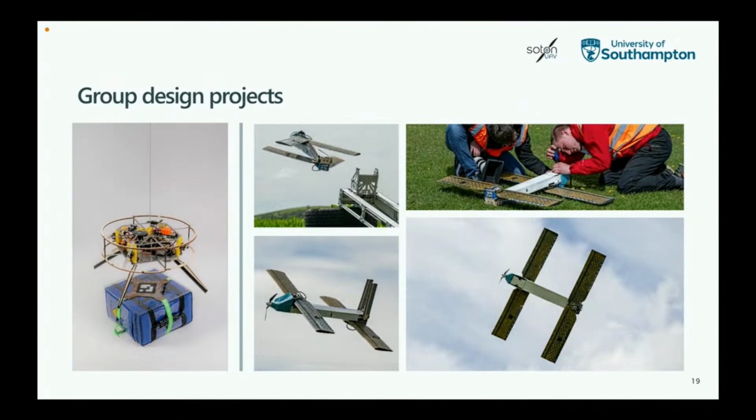And then on the right, we have a design brief which was titled to get them to make a person-portable UAV. They'd have a system where they'd take the catapult and the UAV, carry that around with them, set it up and launch it. This utilized the ArduPilot launch systems, so it delayed triggering of the servos to release the tail fins, and also delayed the motor spin up to make sure there's no fouling on the catapult.